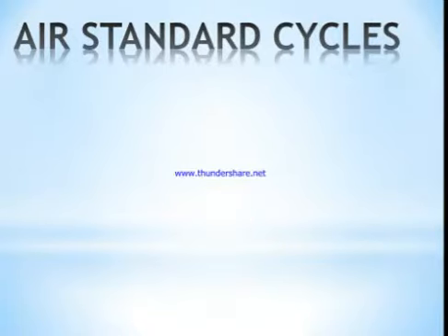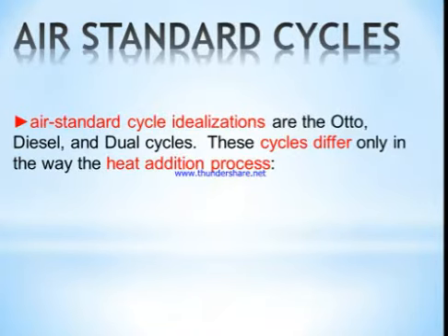Hello everyone, today our topic is air standard cycles. Air standard cycles are thermodynamic cycles where the working fluid is air, which behaves like an ideal gas. Air standard cycle idealizations are the Otto, diesel and dual cycles. These cycles differ only in the way of the heat addition process.